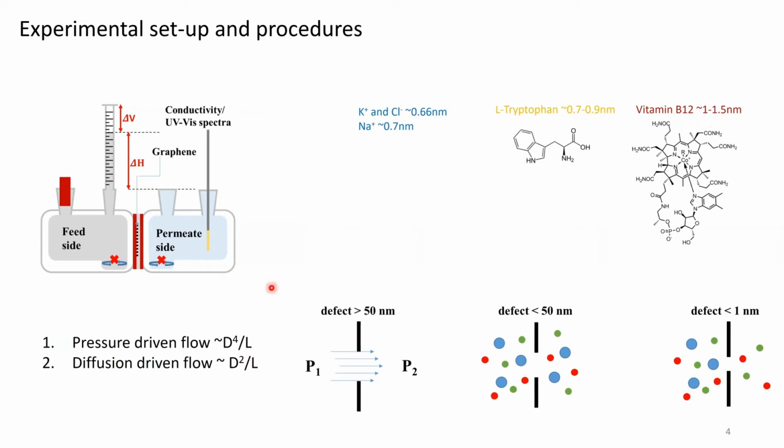In addition to that, we're leveraging simple scaling laws, where pressure-driven flow scales as d^4/L, and diffusion-driven flow scales as d^2/L. And the key aspect we're going to be looking at is diffusion, which allows us to probe defects that are less than 1 nanometer.